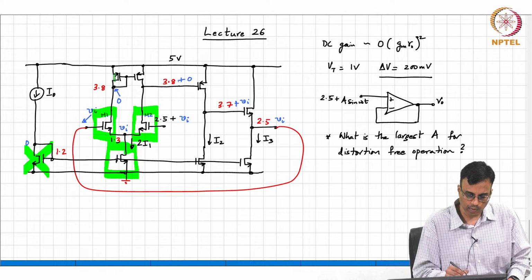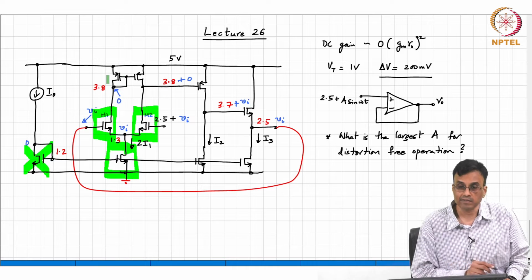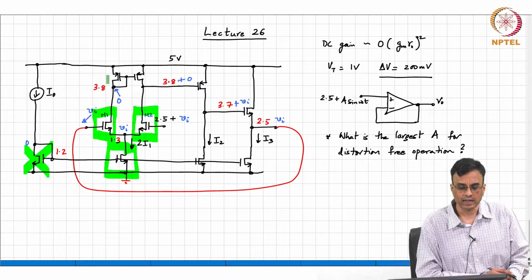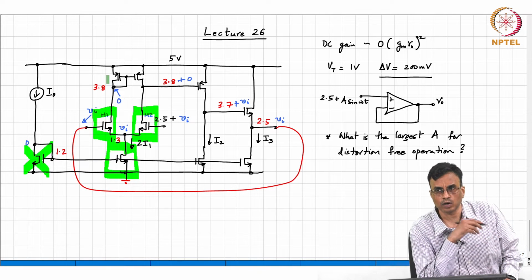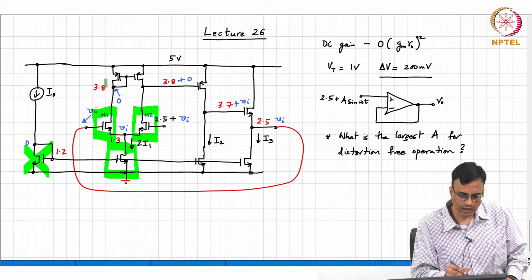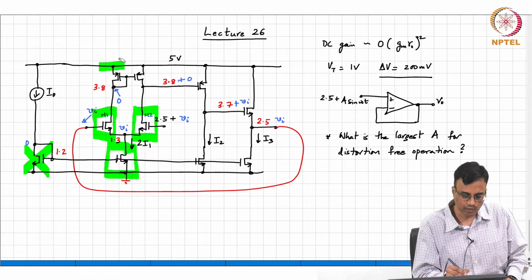What about the PMOS loads? What about the one on the left? The diode connected PMOS load. Why? The source drain voltage is not varying at all, right? But what about the incremental current? Is there a possibility that the transistor goes into cutoff? Is everybody clear that this transistor is not of concern at all?